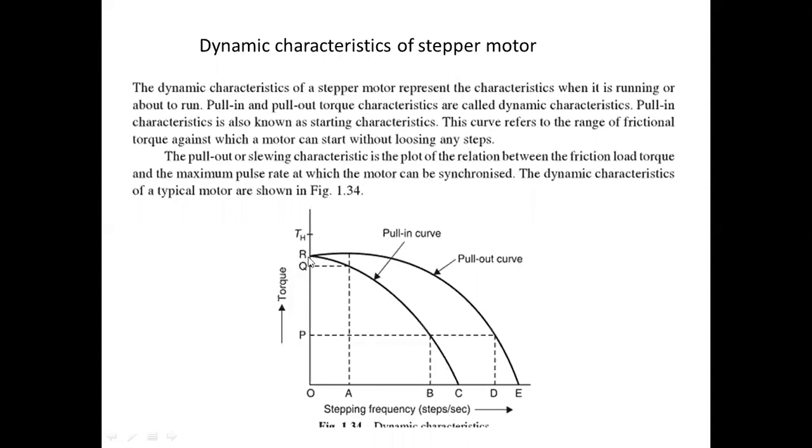It starts and the torque value is okay. After that, what should happen? It drops with respect to the stepping frequency. You have to consider that as the pull-in curve, and next is the pull-out torque.